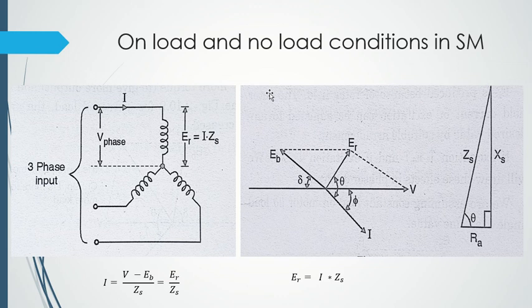Because of this inductive element, the current I will lag my resultant voltage. How much will it lag? Because the inductive effect is too strong and resistance is almost negligible, it will lag by around 90 degrees, a case similar to pure inductive effect.